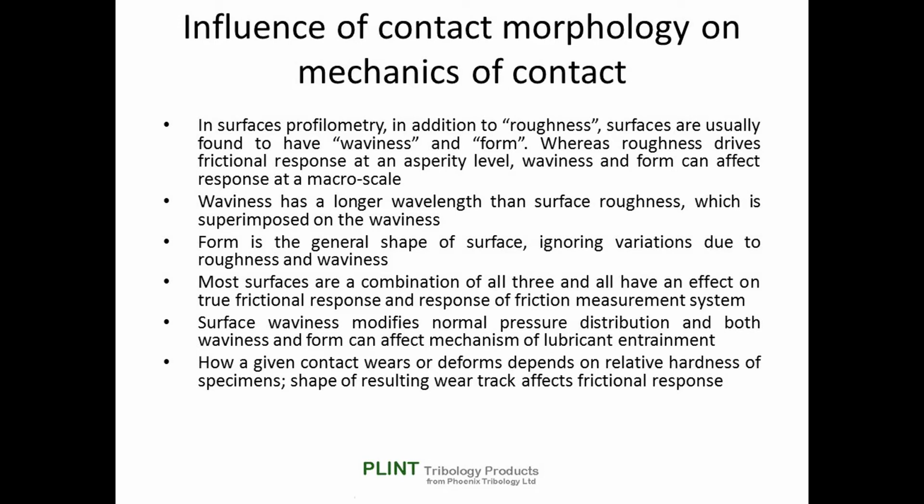Form is the general shape of the surface, ignoring variations due to roughness and waviness. Most surfaces are a combination of all three, and all have an effect on the true frictional response and the response of the friction measuring system. Surface waviness modifies the nominal pressure distribution, and both waviness and form can affect the mechanism of lubricant entrainment.